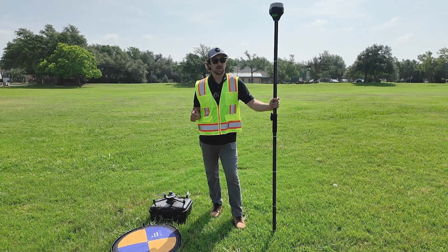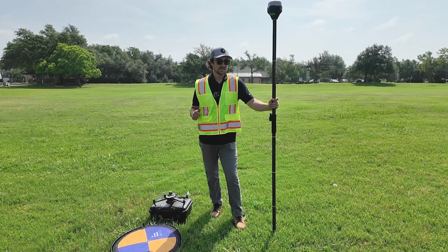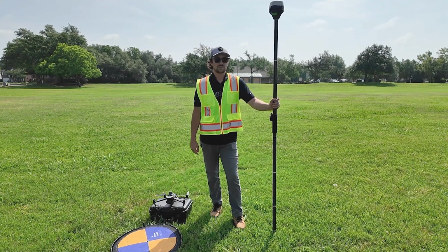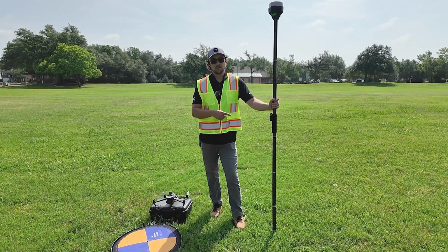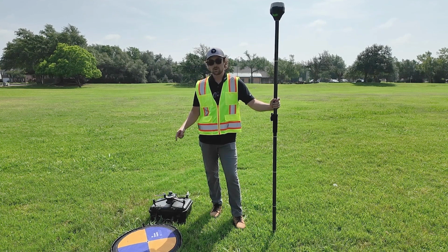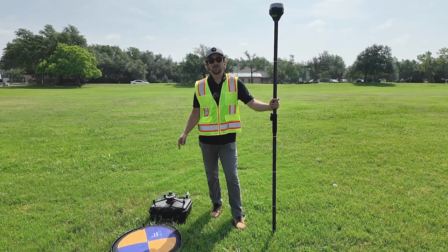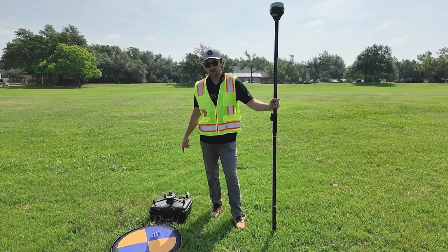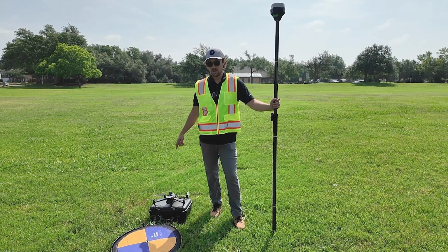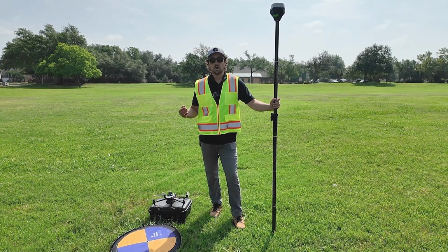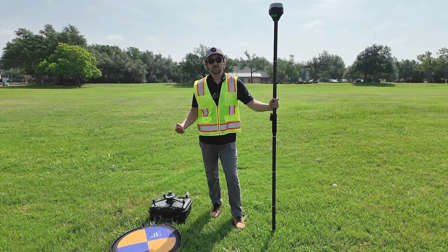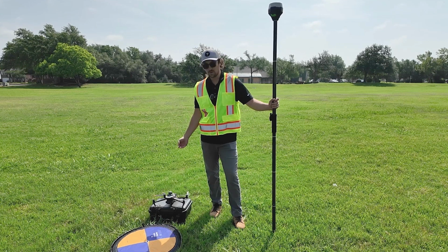Some of the equipment we have on site today is an MLID RS2, and we're going to be collecting the actual coordinates of these ground control points and these checkpoints that we're going to be laying out today. And we also have a Mavic 3 Enterprise with RTK module, so we're going to be flying this site with RTK as well. Hence why we're able to do a single GCP workflow, because we do have an RTK enabled drone that we're flying.